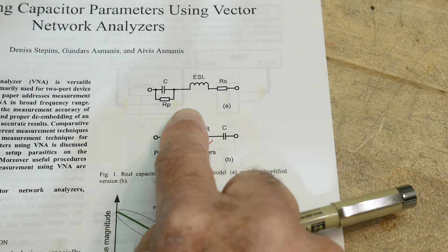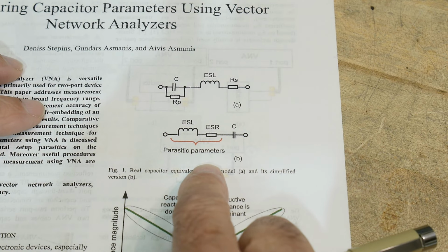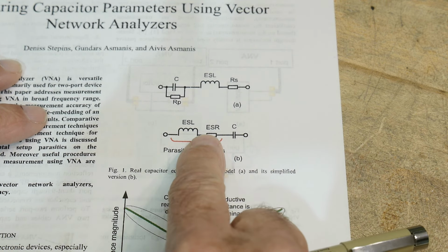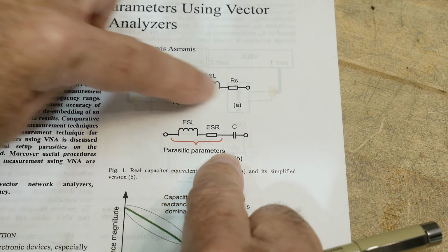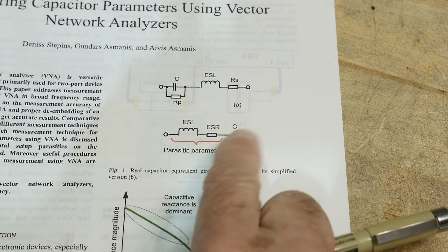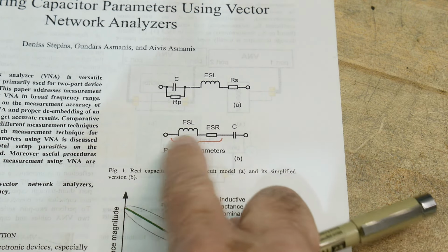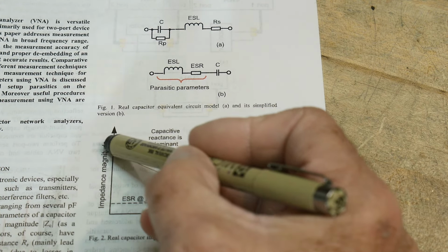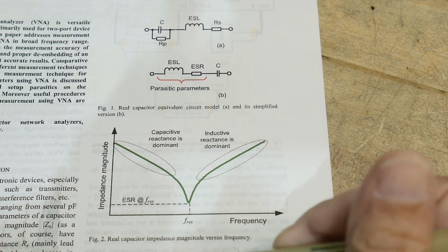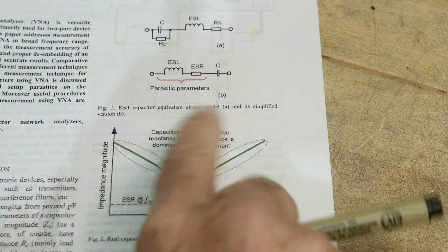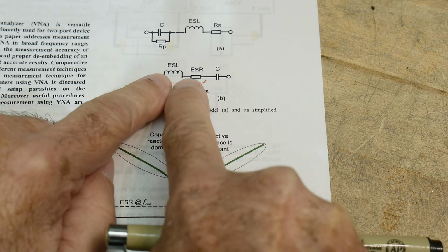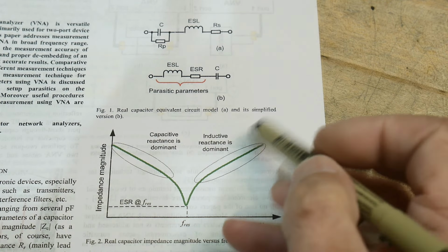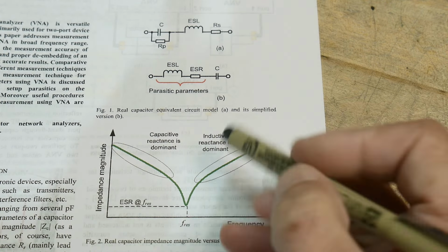When people do capacitor models, they generally model it this way, that there's an inductor, a resistor, and a capacitor. But it's actually a little more complicated than that in the real world, but this is what we're thinking about, okay? And so here he gives a nice graph, should look very familiar with the graph I just drew, where when the capacitor is doing its job, it's falling like this, and then because we have both, that little bit of inductance will start to work at super high frequencies, and you'll start to get this again, right?